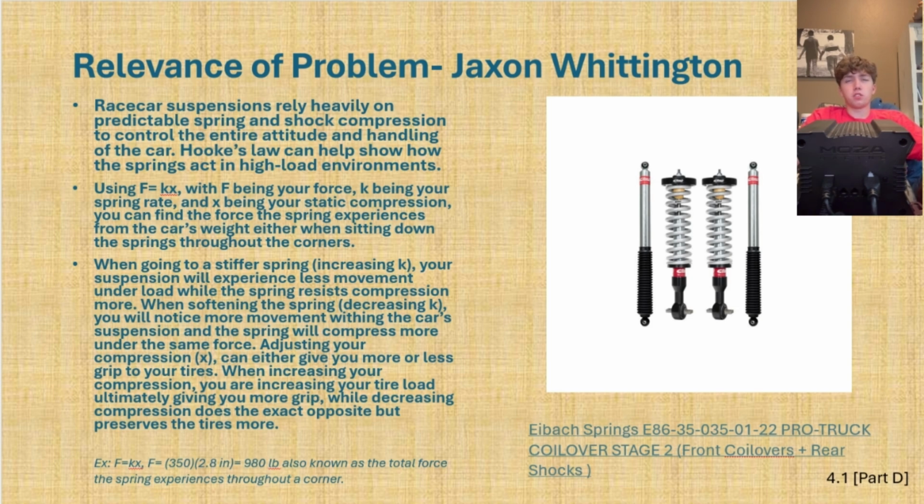So if you have a stiffer spring, you're going to have more grip, but you're going to eat up your tire more, versus if you have a softer spring, you're not going to eat up your tire near as much, but on the flip side, you're not going to have near the amount of grip.